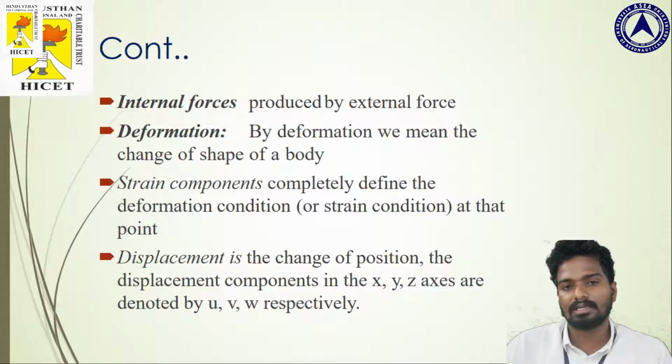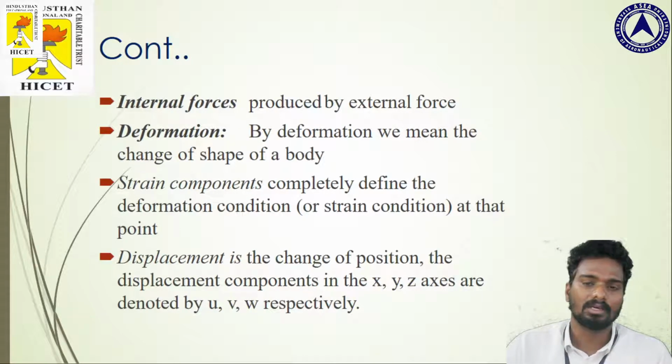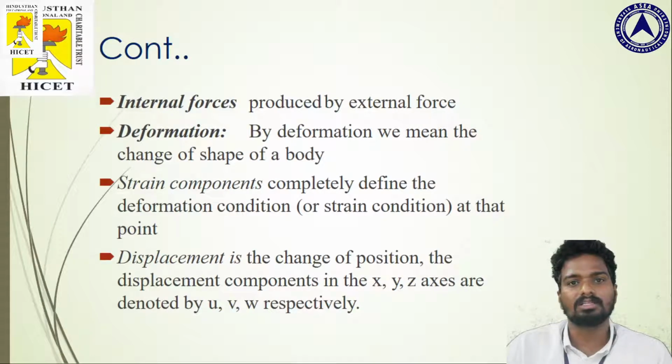As we said earlier, internal forces are nothing but the stresses created in the body due to the external forces, and the deformation is simply the change in the shape of the body or the change in the geometry of the body. Thus, it can be classified into strains and displacements. You know very well, displacement is the change in position of the body, and the strain is the resultant of stress. So it defines the deformation of any body due to the external forces.